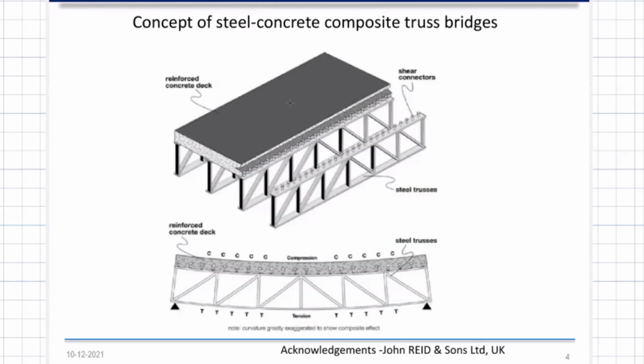Very nicely, if I have headroom, I can use a steel concrete composite truss bridge. Again, the same concept. I have an RC deck. Of course, I'm not talking about the toppings that we have, the black top, the weathering coat; this is implied here. So I have a deck slab supported by a truss system. Now, this is integrated using the shear studs. I don't know whether you are able to see the shear studs. Don't worry, I'll be showing a couple more examples of shear studs.